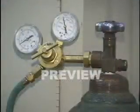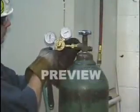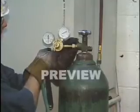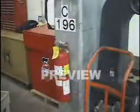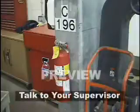Be careful about fittings or connections. Before any connections are made, inspect the cylinder carefully. Do not change, modify, repair, or tamper with the pressure relief devices on cylinders. During welding or cutting operations, keep the work area clear of debris and keep a fire extinguisher nearby. Talk to your supervisor if you have any questions or concerns.